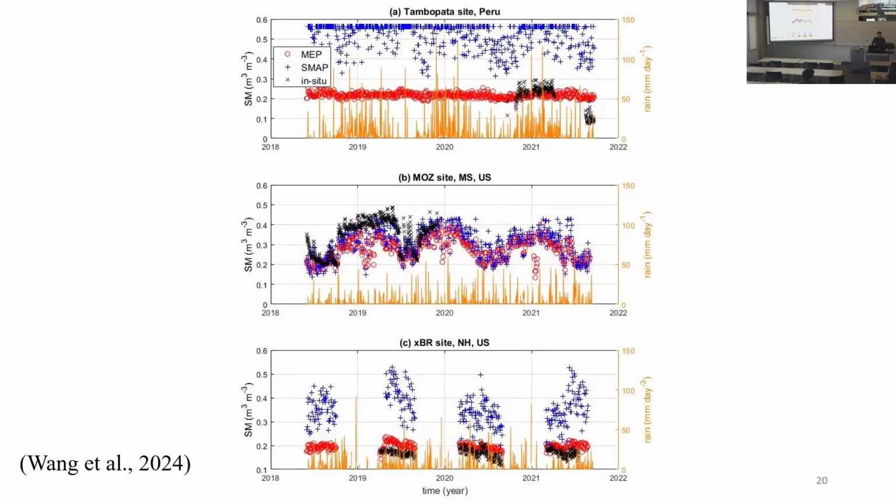So the stars are the estimates from the SMAP satellite, while the black ones are the field measurements, so that's a significant bias. But that's for the tropics. We're looking at the vegetated region, so that's the goal. So one of your lessons is: don't use SMAP for vegetated surfaces. They do retrieval, but they tell you there is large uncertainty. Yeah, very large biases.